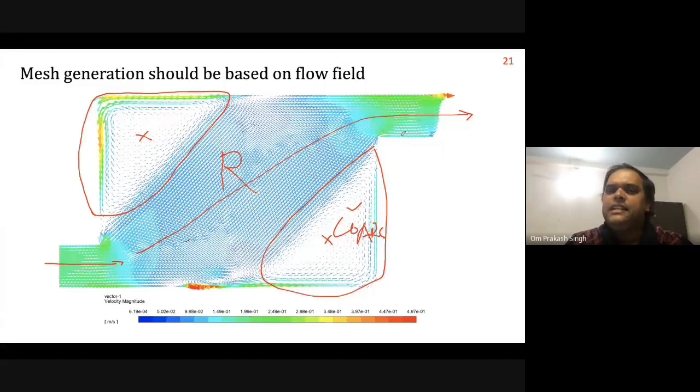And measure, let's say, whatever you want to measure, any heat transfer quantity or losses or Nusselt number, depending upon your physics, you start monitoring. So first start with a mesh one, it's not much refined. Then keep on refining slowly, this region only.